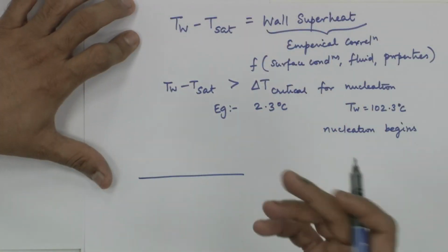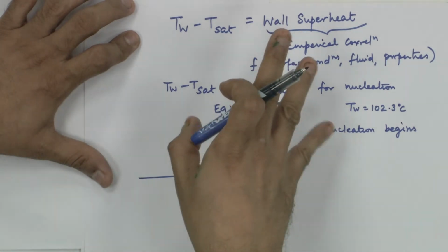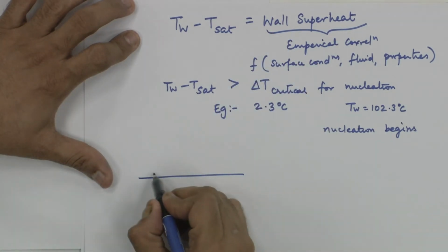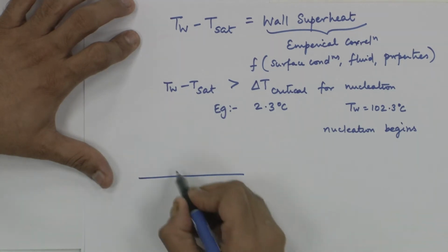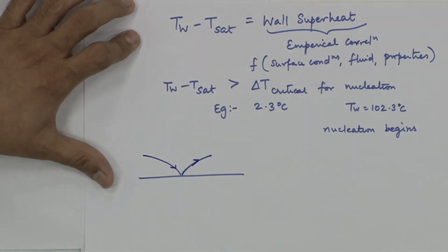The pan is the same, the batter is the same, but in one case you are unable to spread the batter nicely, in other case you are able to do it. It depends on the temperature of the heated surface. The pan, when it is very, very hot, what happens is the batter, let us say instead of batter, droplets, the water which the person sprinkles on the pan, the liquid is not able to come in contact with the heated surface, it will just bounce from the surface.